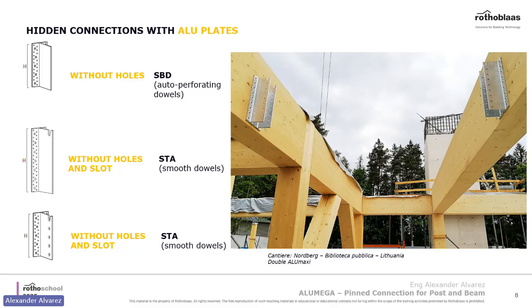But then you also have these types of hidden connections. We have the Alu series: the Alu Mini, the Alu Midi, and the Alu Maxi. They are knife plate connections, and there are many ways to install them, either with our self-drilling dowels, or SPD, or our smooth dowels. You can either drill, like you can see in the middle picture.